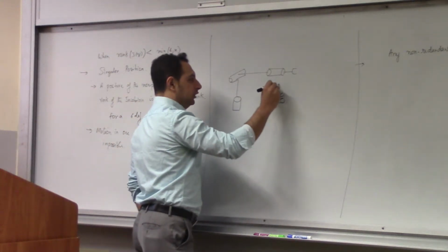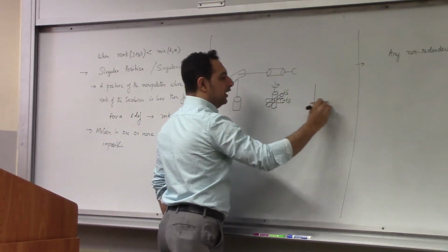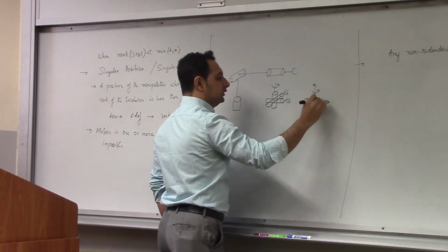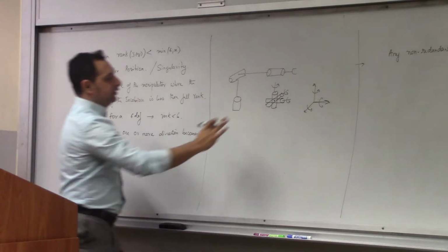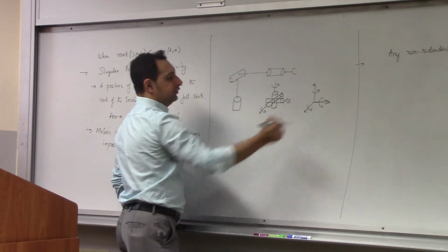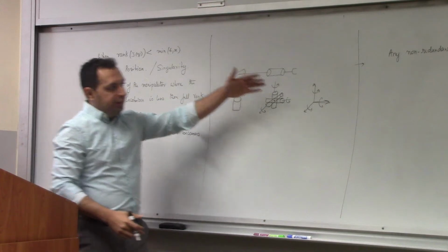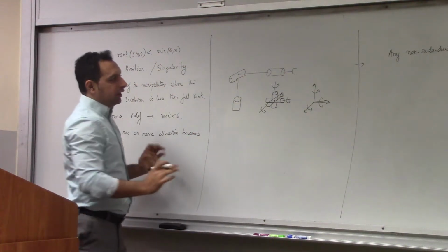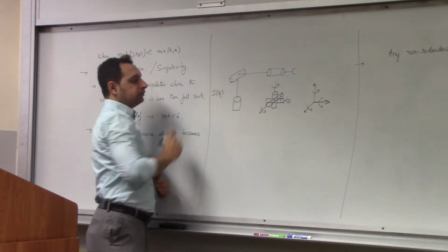So this is motion along this. This can be motion along. Okay, so we have motion along all 3 independent axes, x, y, and z, like this, and like this, right? Because these 3 axes are oriented like this. If you want, you can assume this to be in this direction. So it will relate to this thing. Okay, so now you can rotate this wrist, and you can have phi, theta, and psi along all 3 axes. So it's a completely spherical wrist. Okay, so this is one posture of the Jacobian. Let's call this J of Q1.